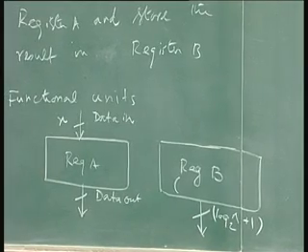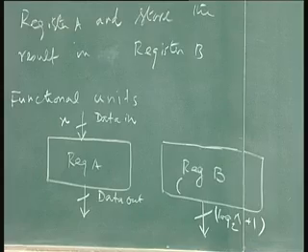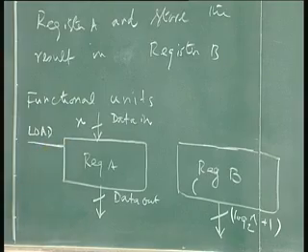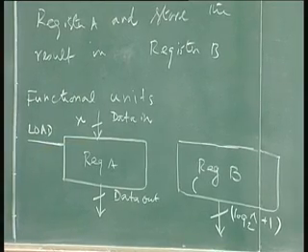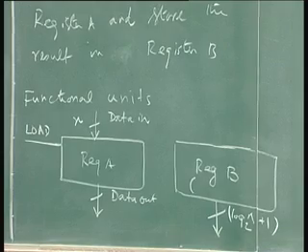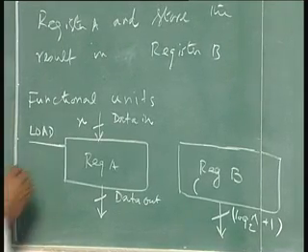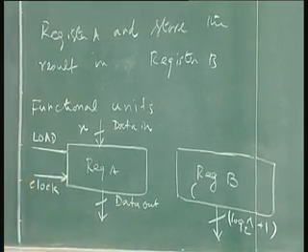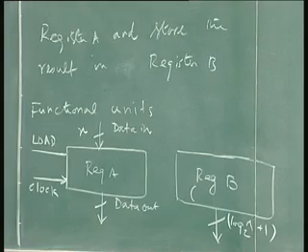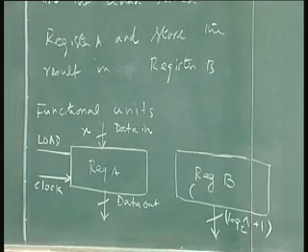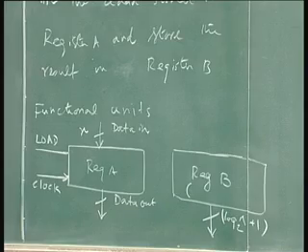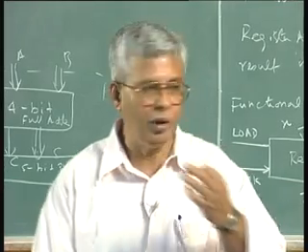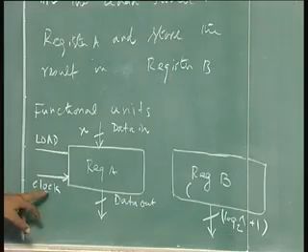Now look at A. A is a register which will store the data, so it should have a loading feature, right, so load feature should be clocked, because only then it will load. I will assume all of them are synchronous operation to avoid confusion. Loading, clearing, all the operations will be synchronous. You know what I mean by synchronous? Along with the next clock edge. As soon as the signal is given, it does not do the job, it waits for the next clock edge and does the job. So load is synchronous loading, that means when I want to load a new value, I put the value here and put load on one and clock it, next time it goes.